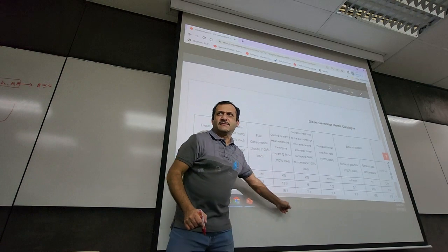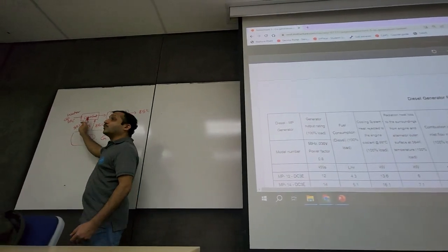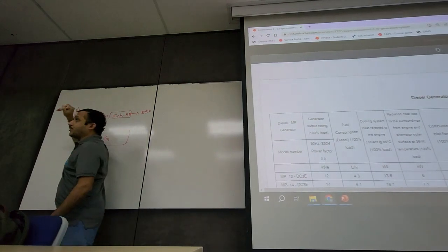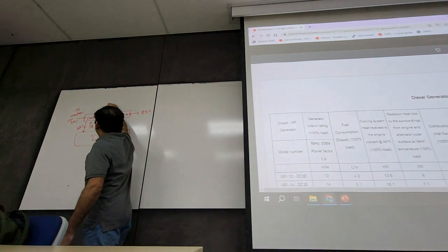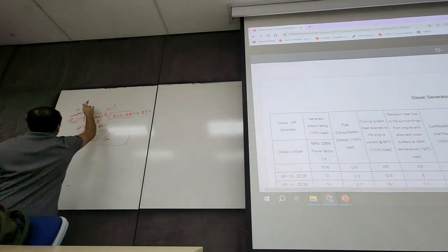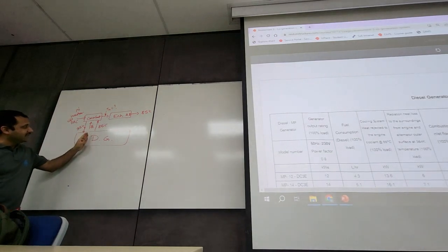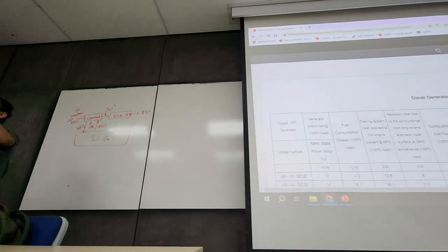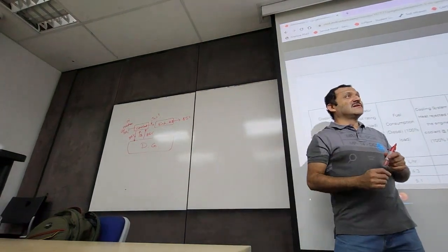Okay? So that amount of Q dot, if you know how much Q dot is going in, you know the mass flow rate of water, you should be able to figure out that temperature. Because you see that Q dot, what we are assuming is that all the thermal energy that is given by the coolant is being absorbed by water. That's one of the assumptions written in the assignment. The assignment asks you to make that assumption. Okay?